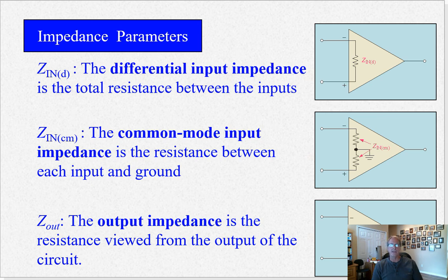And the fact is that all of these input impedance and output impedance parameters are frequency sensitive. They're not just pure resistors. There's some capacitance in here and a little bit of inductance, so they're complex. Fortunately, that doesn't come into play as much as just the frequency response of the amplifier, which again, we look at towards the end of the course.